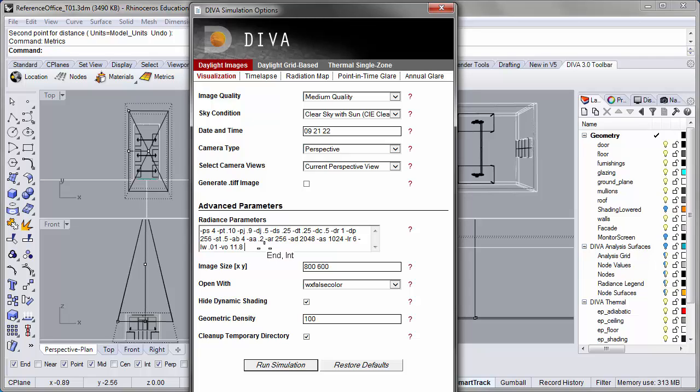And so to do that, we do another space, and the argument for that is I. And so we do dash I. The dash I is basically just telling Radiance to, again, just make sure that it represents the value for every pixel in our high definition image as illuminance as opposed to luminance. And so we're ready to run the simulation.